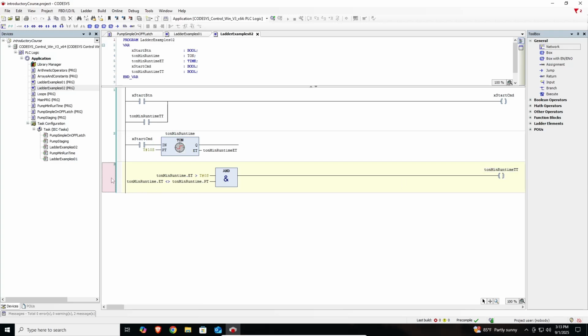So I'm actually manufacturing that here, and I'm going to catch that into this run, so that this start command will continue to stay on, or be true, even if we lose the start button, as long as the timer is on, right? Or this could be the start signal, actually, not a button, because a button you will press and you will let go. It will be more like the start signal.